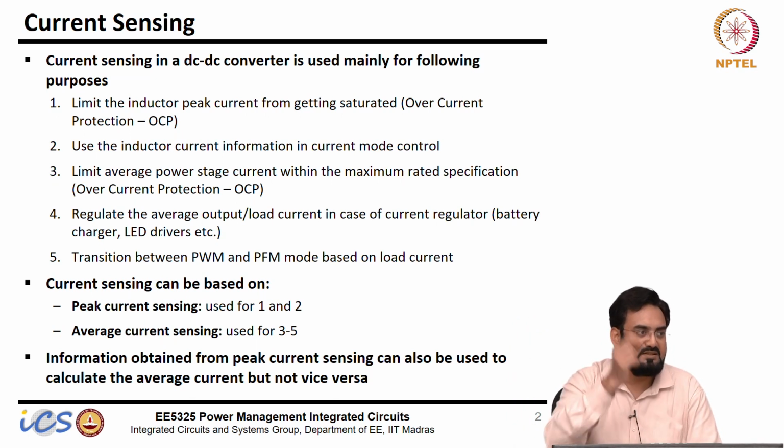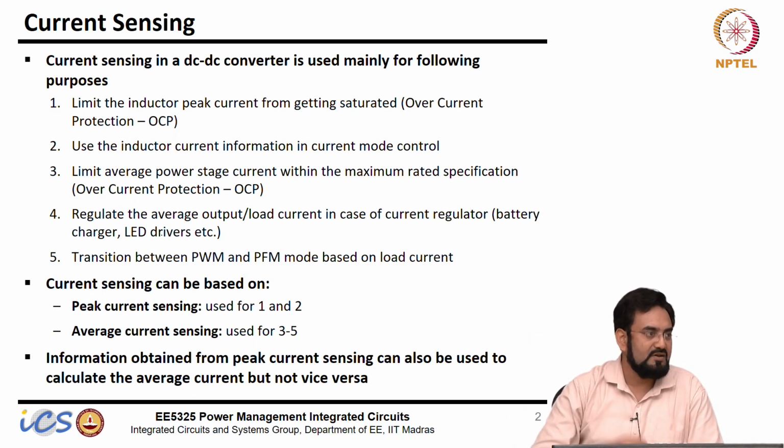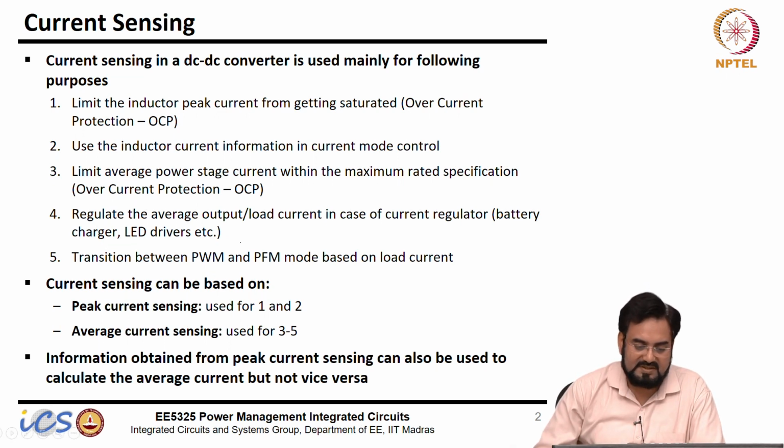Even a small change in the LED voltage can cause a very large change in the current, which means your brightness will change and it may even heat up, even if you change the voltage by 100 millivolt or so. So that's why it always requires regulated current.